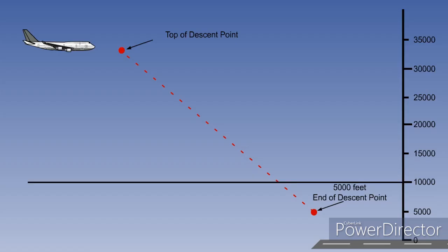The economy profile is economy descent to 10,000 feet. Then, to reduce speed to 250 knots or below. The change from Mach to indicated airspeed hold during the descent is also automatic. Ideally, the computer will use idle thrust and optimum speed values, but these can be varied to take account of unforeseen wind conditions to keep the aircraft on the correct descent path.